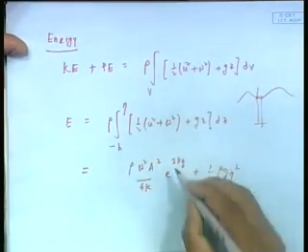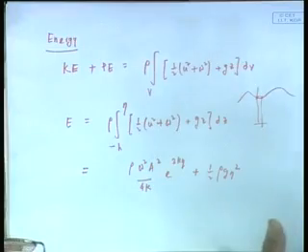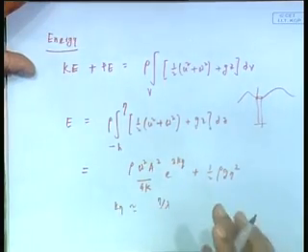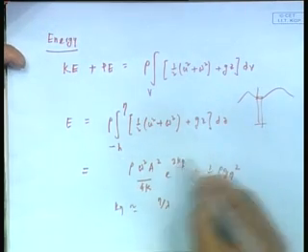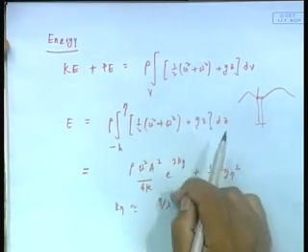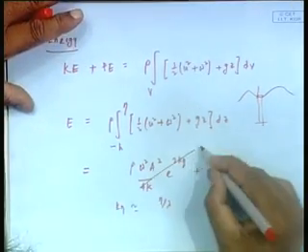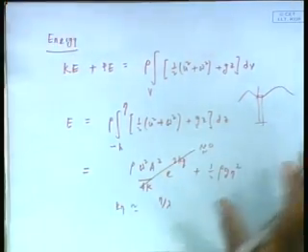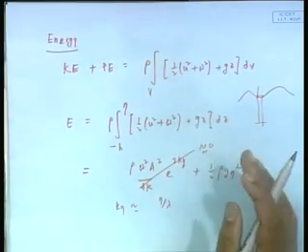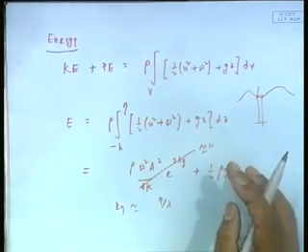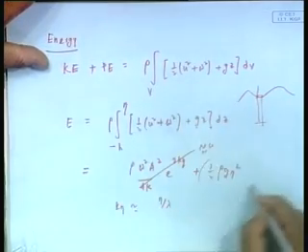Now, this part, k eta, what happened? Remember, we have said k eta is small, it is small amplitude wave theory. Eta is height, k is inverse of lambda, so k eta is proportional to eta by lambda. So it is e power of some small quantity, twice e square. If I call k eta an epsilon, it is e power of 2 epsilon. So, this part becomes very small. In linear theory, it is consistent to neglect that, because this is a second order term: k eta is of order epsilon, 2 k eta is of order 2 epsilon. So, we end up getting this relation.